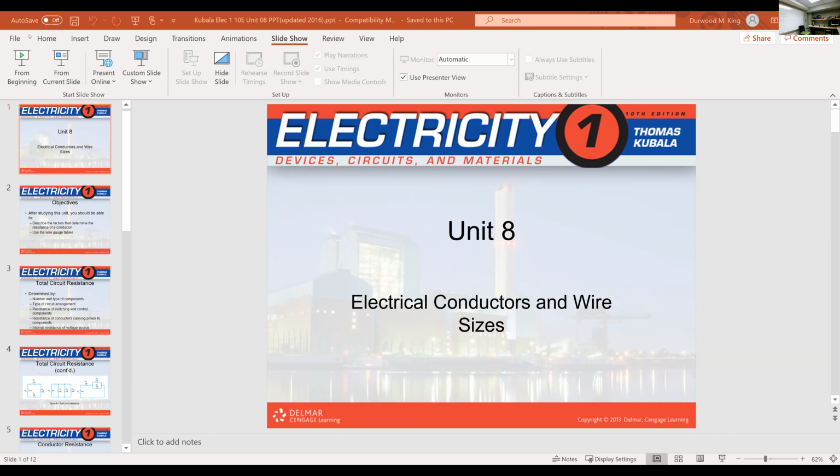Now, they're matching. So that gives you a total resistance of 2 ohms. You see how drastically different that is. That's what they mean by the arrangement. And then when you do a combination, you put 2 6s in parallel to give you 3. And then that 3 in series with that 6 gives you 9. So they give you 9 the way that is.